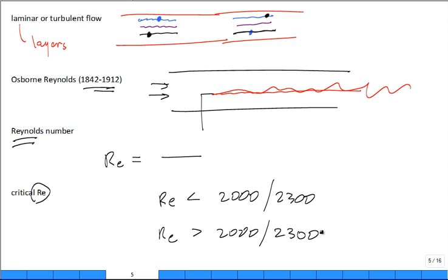Why isn't it just such a fine number you know it to 3 or 4 significant digits? Because other factors come into play. Is there a little vibration in the room where the pipe is? A little machinery running? That helps promote turbulence, a little background vibration. So you have to have a lab which is very calm, no vibrations, no motors running, even on the second floor, 2 floors over, in the basement, so you have no vibrations.